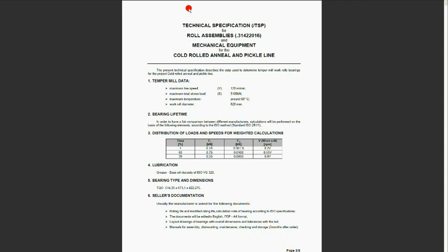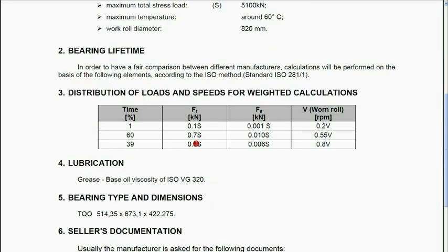According to the customer specification for the application, the bearing is subjected to variable operating conditions, where load varies in magnitude over time with changes of rotational speed. In order to calculate the bearing life, it is necessary to compute an intermediate step related to the variable load conditions. In this case, it is required to reduce the load spectrum of the application to a limited number of simple load cases, in our case equal to 3. Then the software calculates each case individually and applies the time fraction step to satisfy the multiple load condition.